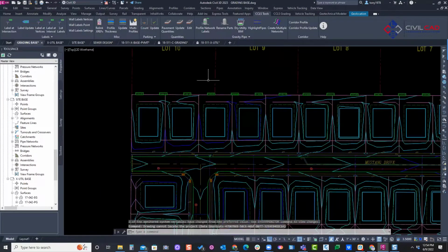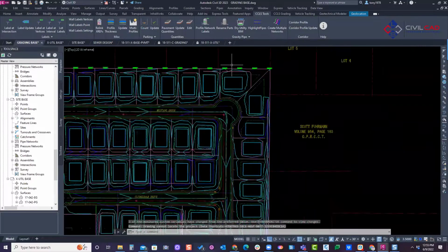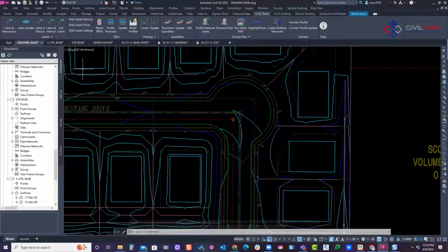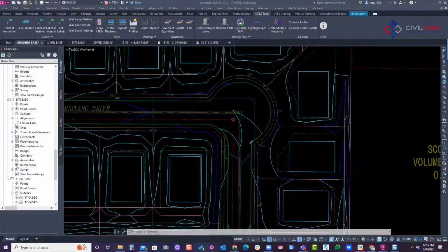The intent of this quarter profile app is for cul-de-sacs. When you model a cul-de-sac, you actually have a feature line here that represents the baseline of this knuckle, not cul-de-sac, but knuckle. It could be a design profile also. And then you've got our main road here that has no curbing. But at this point, they tie together, the alignment, design profile with our feature line.